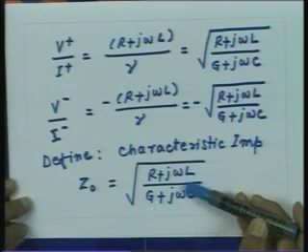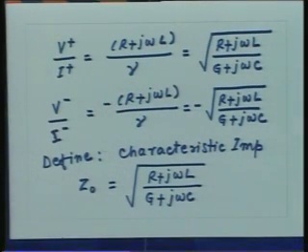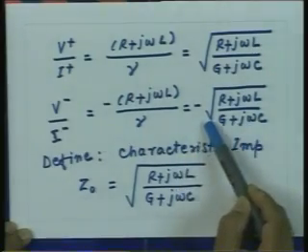So, again concluding that irrespective of the boundary conditions on the transmission line, we established that the forward travelling wave always sees ahead of it the impedance which is equal to the characteristic impedance, and a backward travelling wave sees the characteristic impedance if I look backwards, but if I look forward, then the backward travelling wave will see an impedance which will be negative of the characteristic impedance. So, as I mentioned, these two quantities, gamma and Z naught, are adequate to solve the transmission line problems.